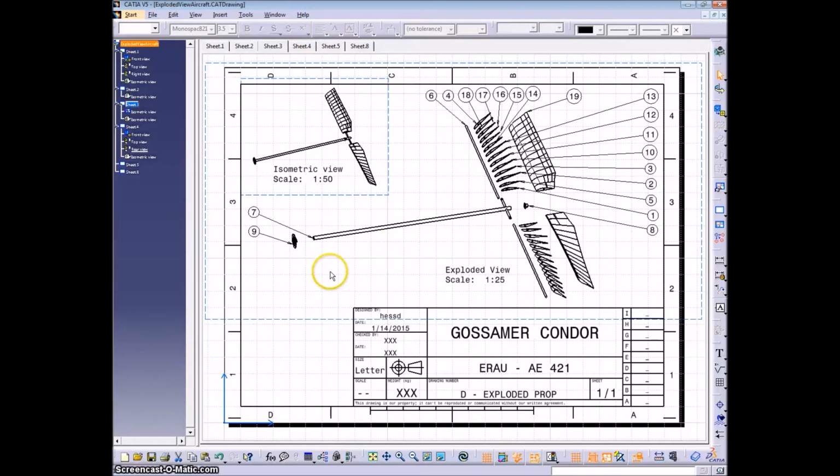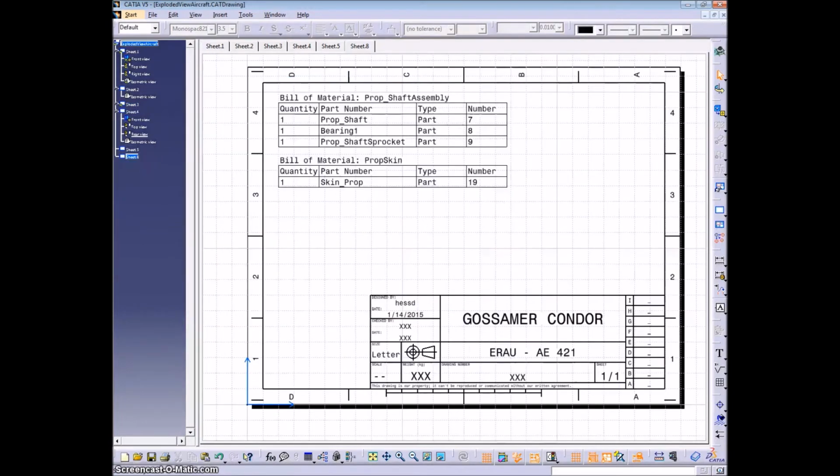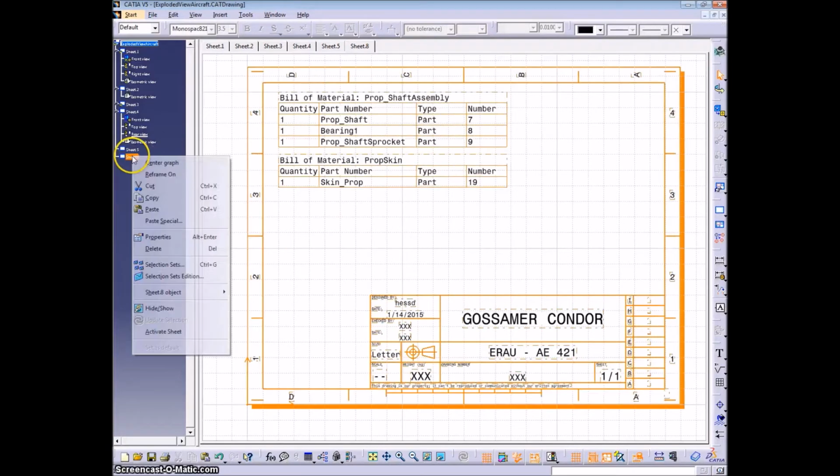Now, you'll notice that there were quite a few numbers here that we didn't end up typing in. Those numbers I had put on this sheet just so that we could identify which rib is which if you were to do a drawing that showed how to align the ribs, and you can identify each rib like that. In this case, a lot of the ribs were used more than once, in some cases 8 times, in some cases 3 times, so that they only show up as one item in the bill of materials.